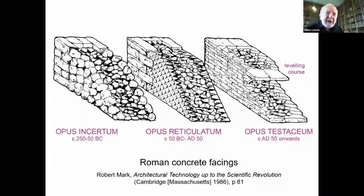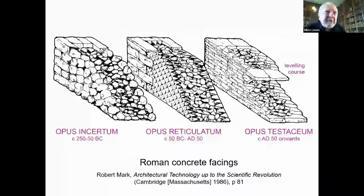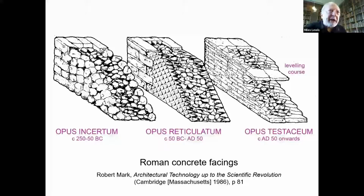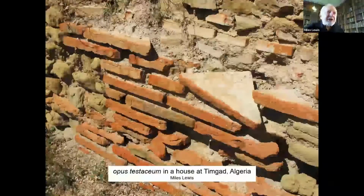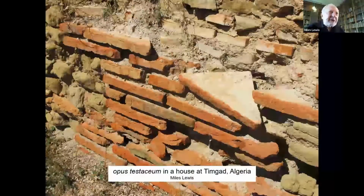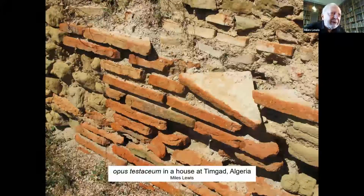The third one, opus testaceum, is made to look on the face of it rather like brick. It is in fact terracotta pieces. They're not bricks, they're triangular. They're shaped like half of a sandwich. But they do the same thing. That shape means that they point in and bond with the concrete in the middle. It's often quite hard to tell whether you're looking at a brick wall or an opus testaceum wall because the face looks exactly the same. But there's an example. You can see the triangular shape which points into the body of the wall.